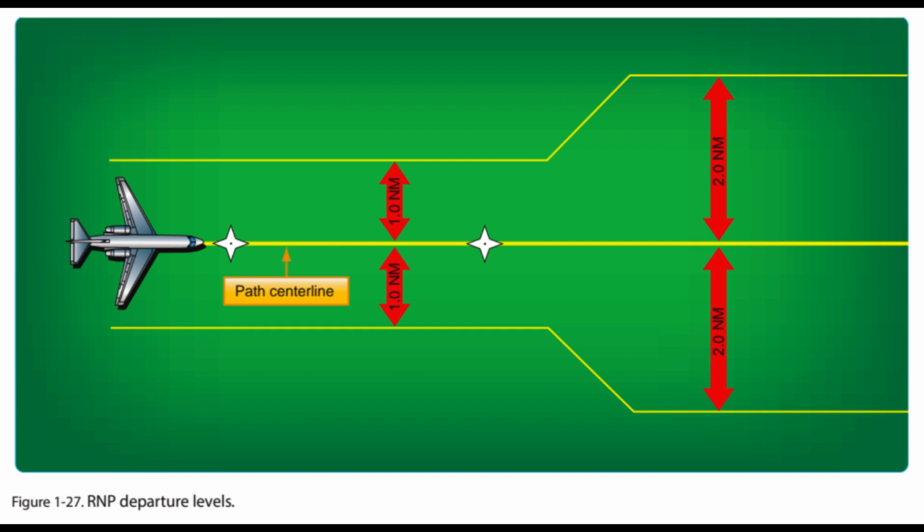No other modification of database waypoints or creation of user-defined waypoints on published RNAV or RNP procedures is permitted, except to change altitude and/or airspeed waypoint constraints to comply with an ATC clearance/instruction, or to insert a waypoint along the published route to assist in complying with an ATC instruction. For example, climb via the Wyelet departure except cross 30 north of Chuck at or above FL210.